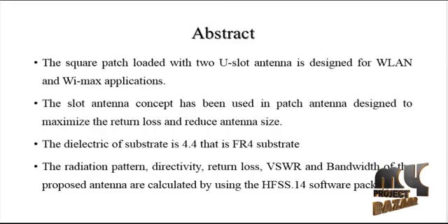The third method, the dimensionally invariant resonant frequency method, optimally combines the features of the previous two and is developed here. It is shown to have better bandwidth performance with minimal or no probe location optimization, and hence is superior to the other two, allowing rapid prototyping.